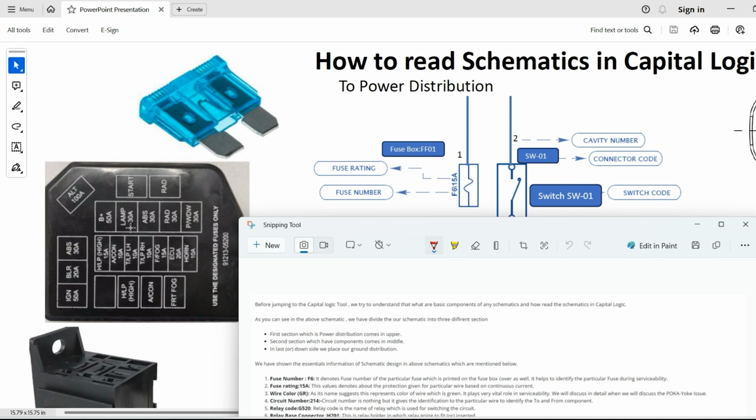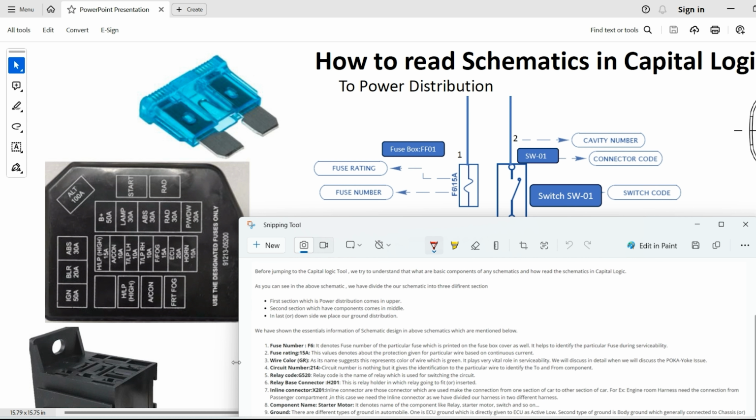That is the identification purpose, to make serviceability easy. Now when you are putting the numbering or name of the fuses, you also have to put the value of that, so that not only the technician but you too are aware when you are creating your schematic.